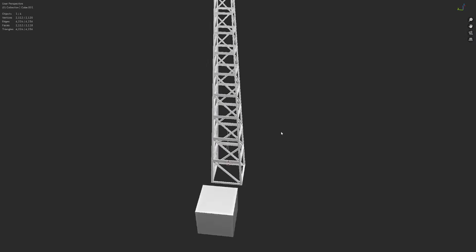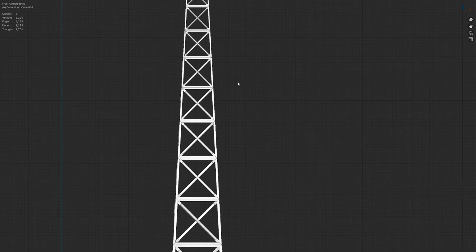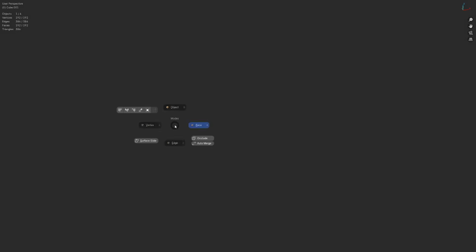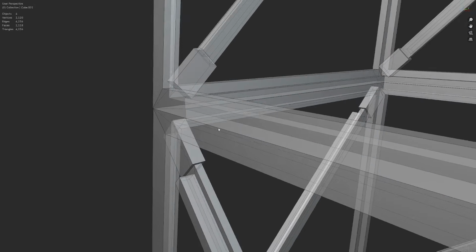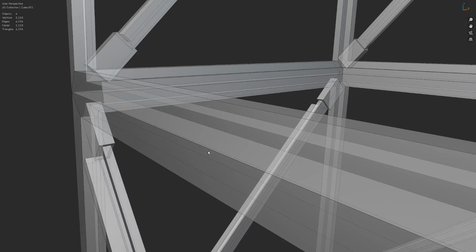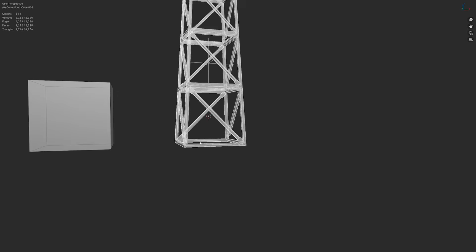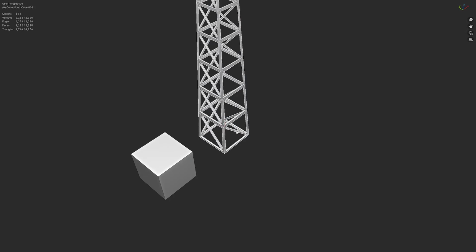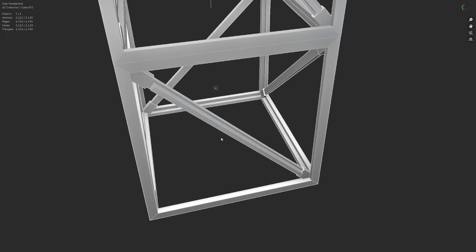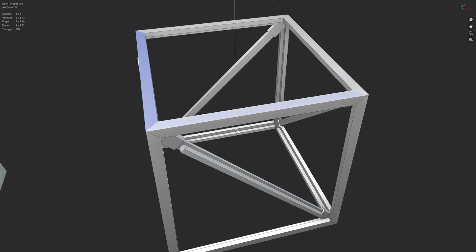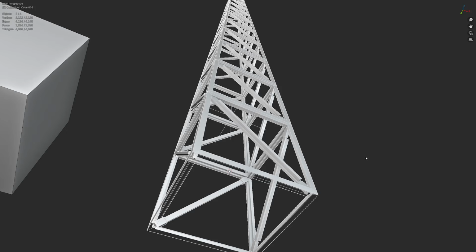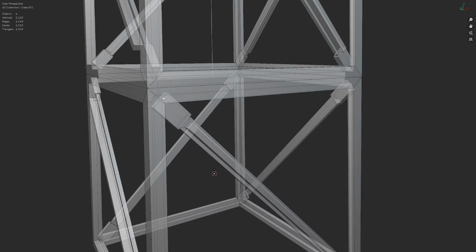And that's it, guys. So these towers, this is a more ideal setup, I would say. You do have to remember one thing here, though, and that is that because of the way we did this, we have these extra faces on the inside here. You don't necessarily need those. So when you're making this piece as a little modular piece, you can model it this way, but when you get done with the whole thing, you can either go through and remove all of those, or you can model it in a way where these here are just deleted on, say, the tops and the bottoms. It's actually much easier to add these back after the array, I think, because then you won't have any of those in the middle there.